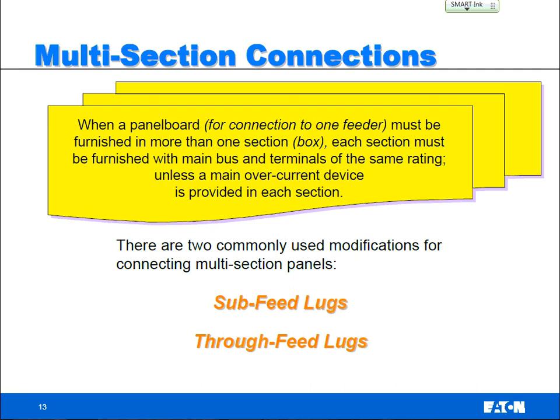A lot of times you get an electrical equipment room where you need more than 42 lights or receptacles coming out of one panel board. So it's common to have 42, 84, or 126, I guess, 1, 2, and 3 panel board tubs all connected together.